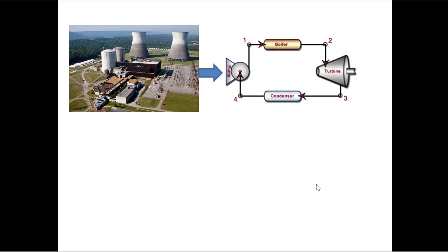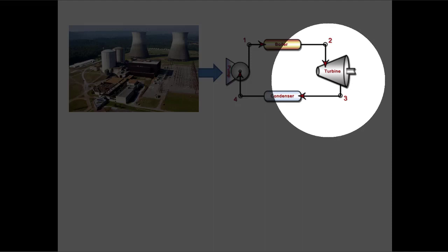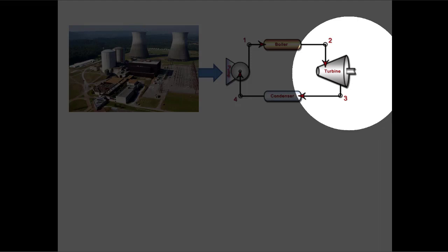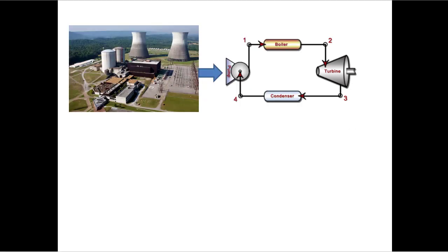So when I think about a nuclear power plant or a coal-fired power plant, it's a series of different processes, from pumps to boilers. Remember, when you give mechanical engineers heat, oftentimes we want to boil water, because if we do that, we get an expansion as the liquid water turns into steam. We run that through a turbine, and it's that turbine that gives us usable energy, because as that steam expands over those fan blades, we get a spinning shaft. And we can turn that into mechanical work, or we can hook that up to a generator with our electrical engineering friends and then get electrical work as well.